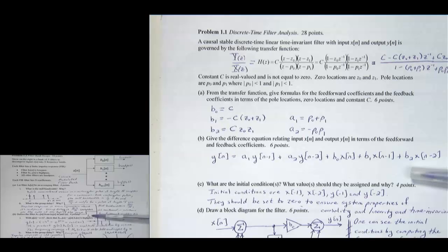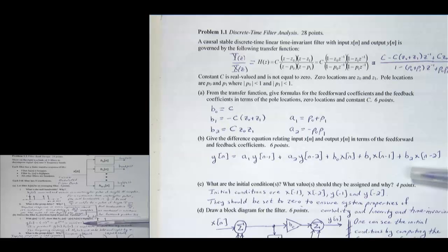Here I draw the product of h0[n] and g[n]. So the product is going to alternate 1, minus 1, 1, minus 1, and it's going to be finite in length, based on the length of h0[n]. And the key is to notice that g[n] is minus 1 to the n, which we've talked a lot about in class, and this is the highest frequency possible in discrete time. This is e to the j pi n, which many of you correctly noted. You can also write this as cosine of pi n. So it's going to alternate 1, minus 1, 1, minus 1. It's the highest frequency possible in discrete time.